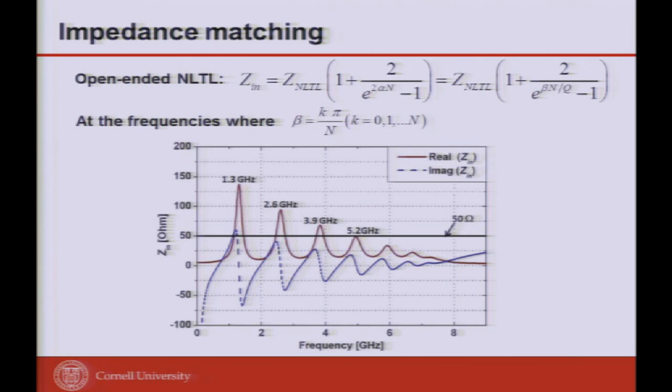And the impedance looks like this. Because of the construction of the wave equations, the impedance oscillates, so there is relatively good matching within a bandwidth of 1 to 5%. That doesn't really exist in discrete elements, but in the transmission line there are windows you can use for impedance matching, relatively broadband within its own frequencies.